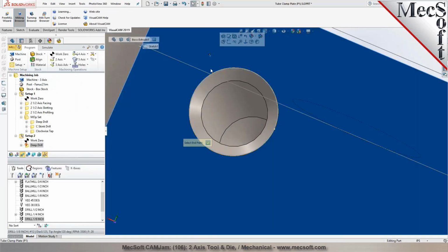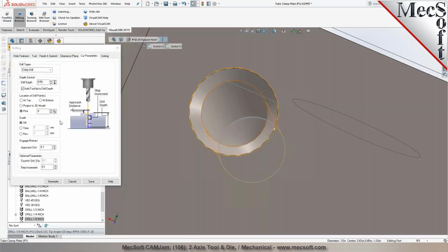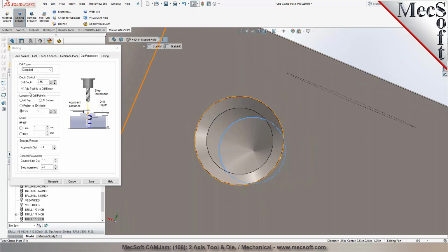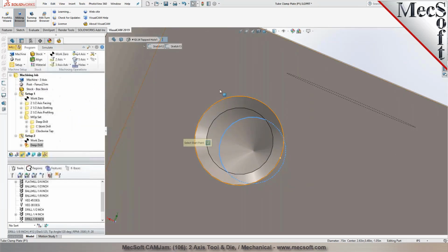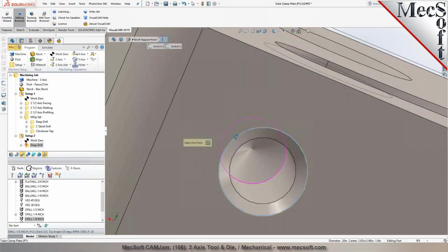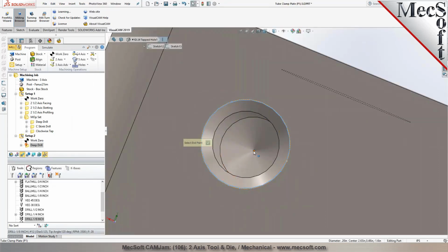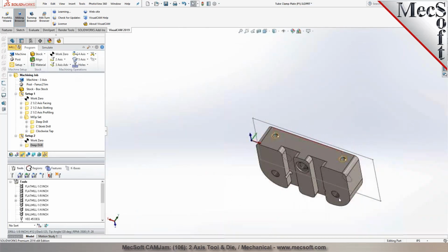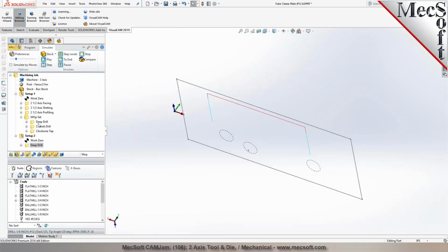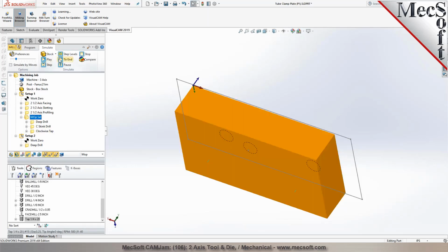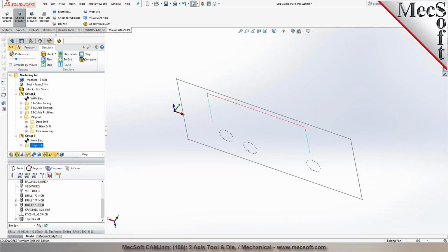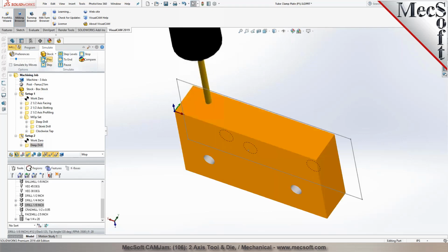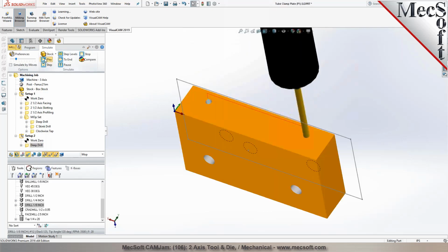So to cut from the top edge right here to go down to this point, and then I said add tooltip to drill depth. So whatever the taper is, it'll go down to this point right here. Or I could clear this checkbox and just pick this point edge and the point down below here to establish the total depth to generate it. Okay. So we have a tool path in here. So I'm going to simulate through this here, and then we'll select and simulate these operations. You can also see the simulation from multiple orientations as well.